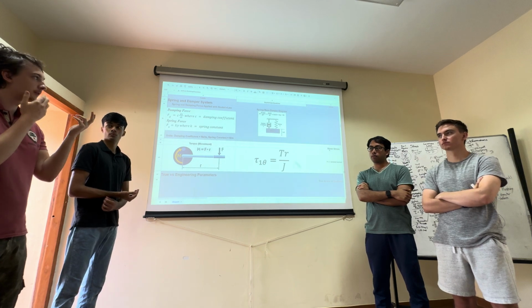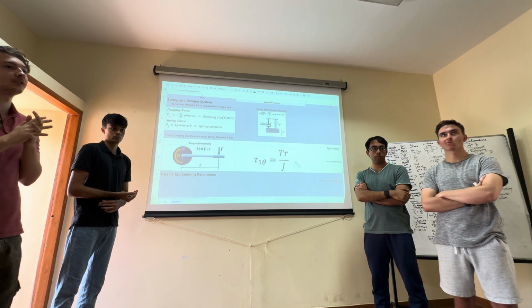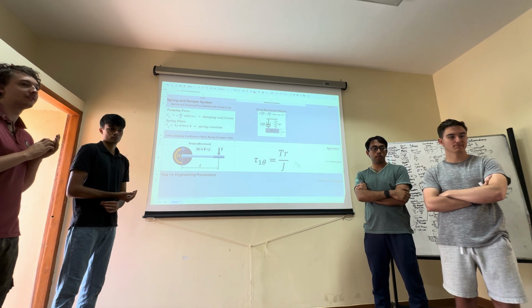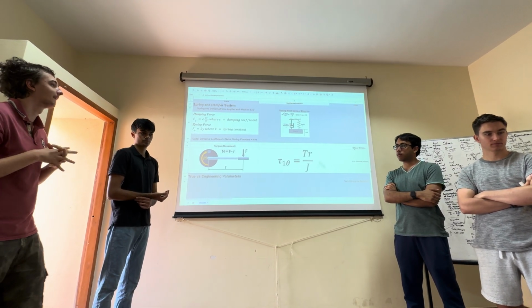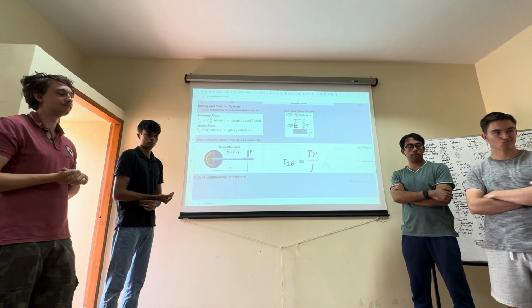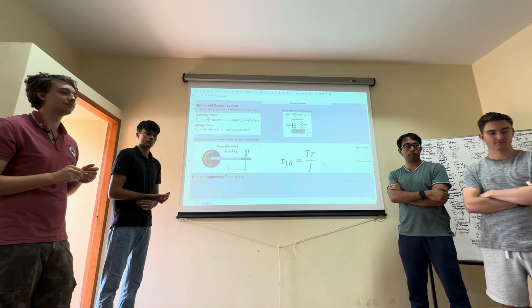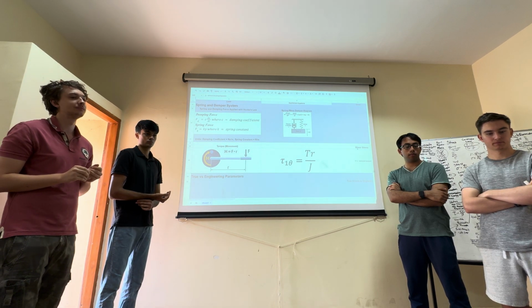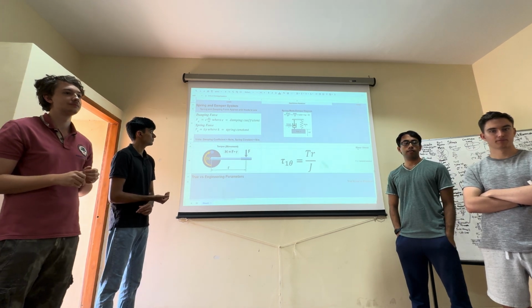If it's a difference in pressures, for example on the inside you have a high pressure, it could be external pressure, as in the case of the submarine, that's probably much more relevant. It's the difference that matters, the external-internal pressure difference. And that's applicable not just to submarines, but also to passenger aircraft which fly beyond a certain altitude, where you have internal pressurization and the outside atmospheric pressure at that altitude.